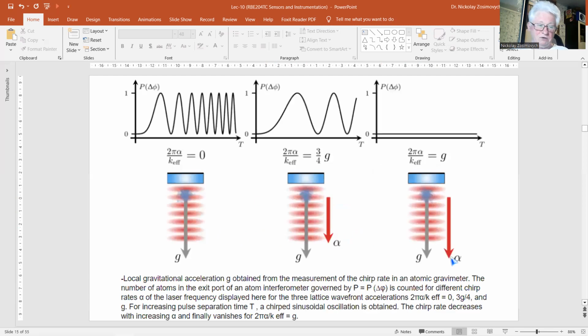The relative accuracy of a non-compensated interferometer in a conditioned room is not much better than 10 micrometers per meter, mainly due to pressure dependence.